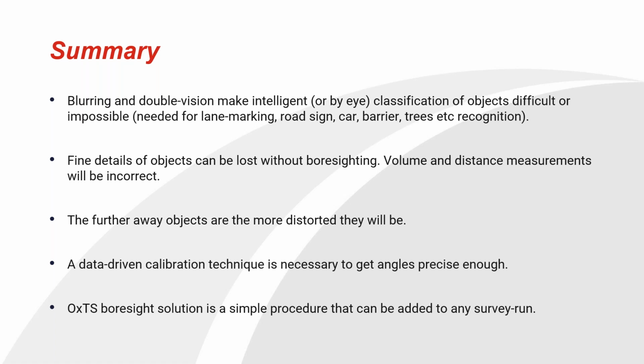And I would just say that the boresight solution procedure that we have with the targets can be done in a couple of minutes. It can be added onto any survey run. You can even use the same file. So it's very convenient, and it really gives you the confidence to just go out and survey. You don't need a huge amount of planning. You don't need CAD models. You don't need all of this. You can be very flexible and very confident that you're going to get the precision that you want.